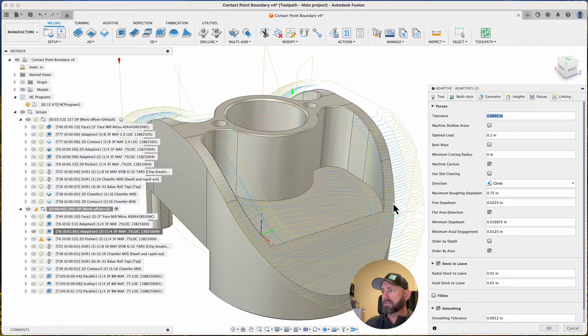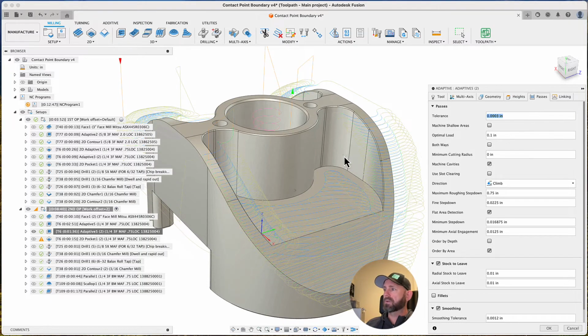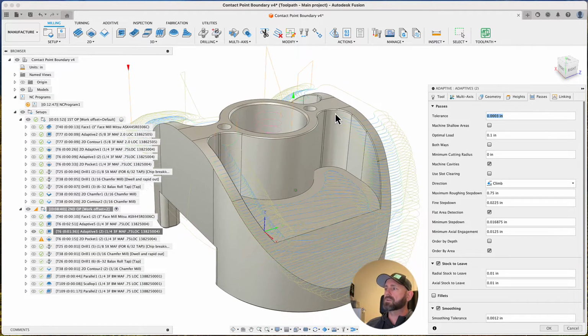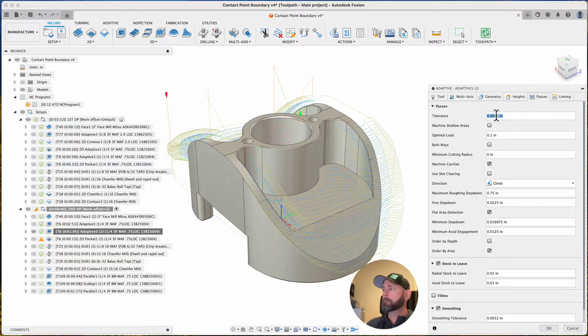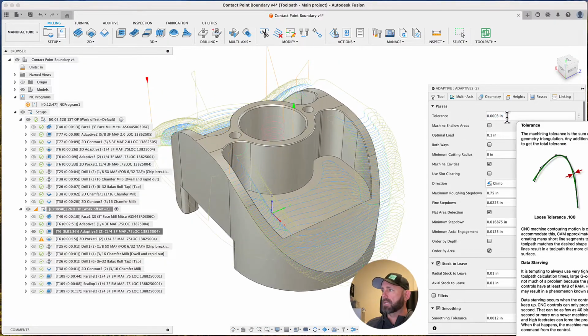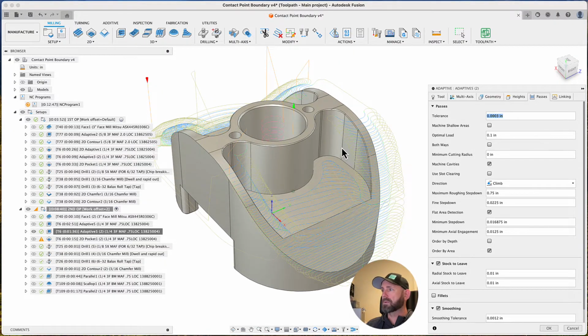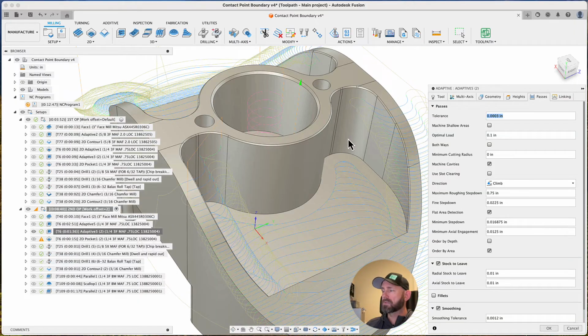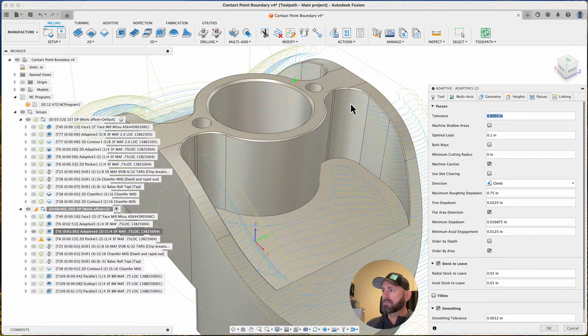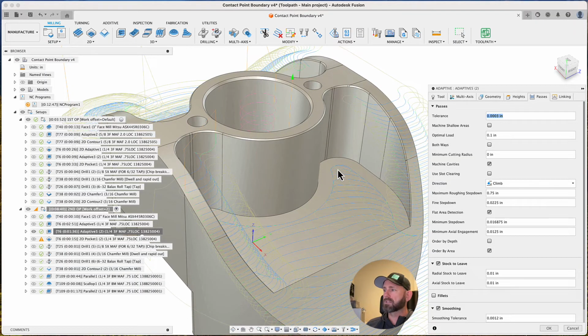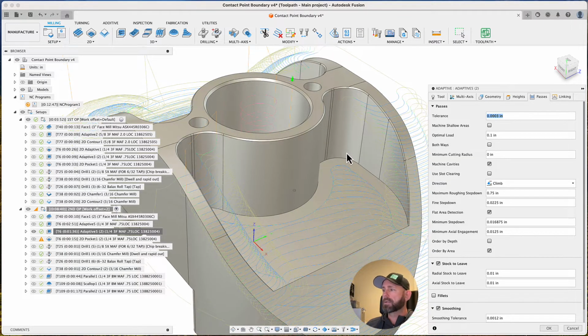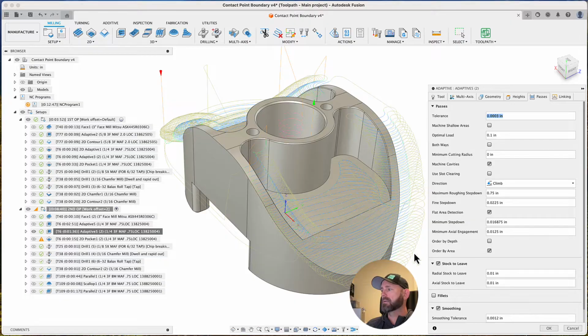As this toolpath is stepping up, it's analyzing that level and saying, where should I go cut? And with a higher toolpath tolerance, it was finding remnants in these corners that it had to go machine. So if I made this 3/10 instead of the other one, which was 4 thou, it cleaned up those ghost cuts, some people just call them air cuts, in the corner. There's no material there because it machined from the bottom up. So that cleaned that up a lot.